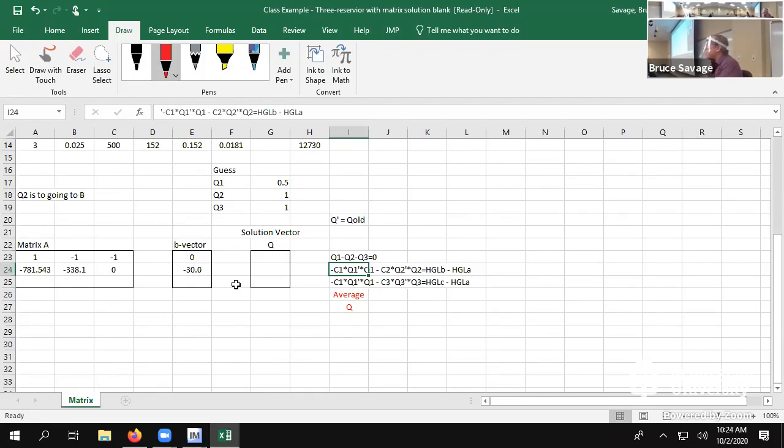Well, if I take a negative number and square it, what happens to it? It goes positive. So if my numerical method tells me that the flow needs to be negative, but every time I stick it in the matrix, it squares it, it's never going to go negative. So is it even necessary to make it absolute? Yes, because that maintains the direction. Oh, because Q times Q, if they're both negative, it becomes positive. But if I take the absolute value of one, then I always get a positive times a negative. So it maintains the direction. Okay? All right, so when I come over here, I'm going to get the same value right there, correct?